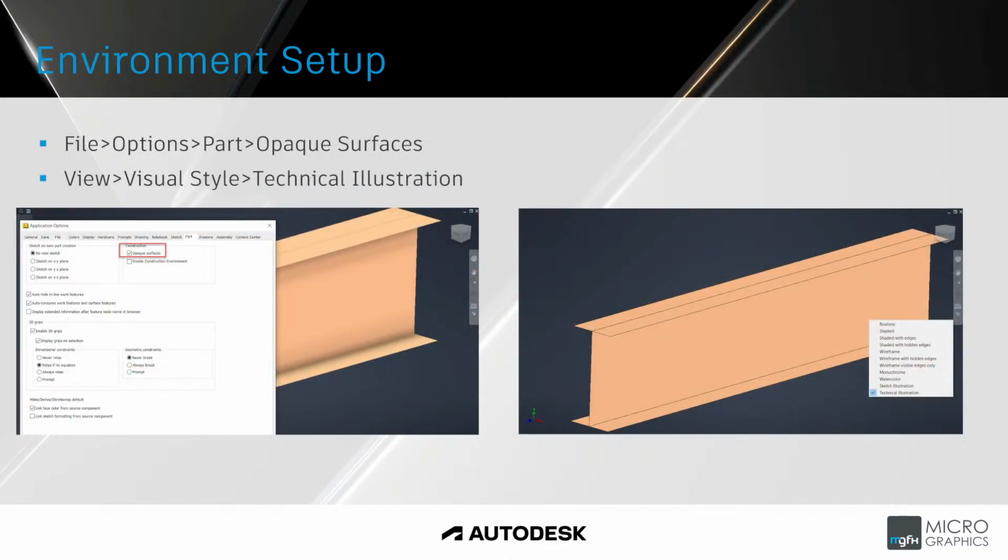Now that is kind of a one-off. If you had to do that, you'll have to do it for every single model. So another option is to have opaque surfaces from the beginning, before you start modeling. If you model up surfaces and then put on this opaque surface under construction, it's only for newly created surfaces, not for anything that you've created previously. So before you start modeling, you go to File, Application Options, Parts tab, and then under Construction, just tick opaque surfaces, and when you draw it up, it's not going to be see-through.